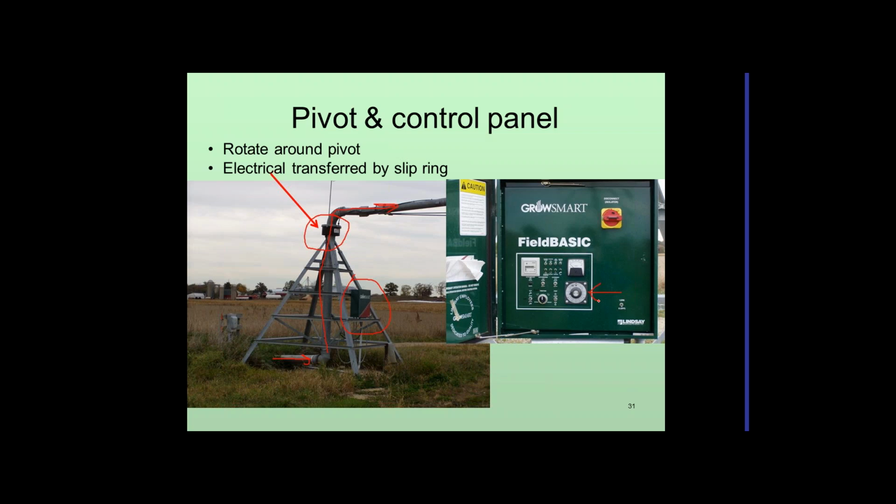This is usually a 2-minute cycle timer, so every 2 minutes it would be moving some portion of those 2 minutes as we go through the field. The center pivot frame is typically anchored to a concrete platform. They do make portable ones that are on wheels, and I believe they still have to have some kind of a ground anchor to keep them centered from moving.